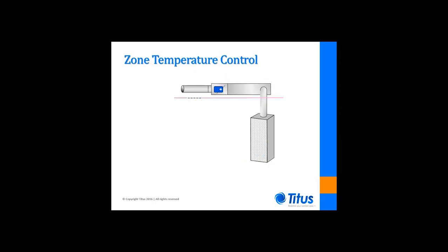A better air quality alternative is to employ a constant temperature variable volume solution. Supply air is delivered at the intended discharge temperature to a single duct terminal, which then throttles the airflow rate to meet the zone cooling demand, establishing a variable air volume, constant temperature delivery of air to the space. It should be noted that the airflow should only be reduced to a level that still assures that acceptable space humidity levels are maintained. This may necessitate the use of reheat when the zone temperature demand drops below the cooling delivered by the supply air at that reduced airflow rate.